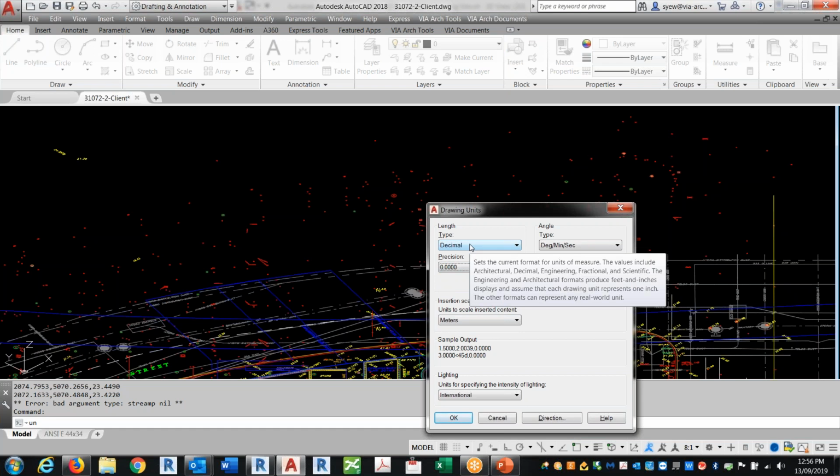Okay, the number, that's the most important thing, because if you put it inside Revit, it'll tell you what number they're supposed to be. If it's feet, square meters, or something else, then you can tell it it's feet, it's meters, or whatever. If you don't do this, Revit just will not function. If you give it, let's say, architectural, it will produce feet in the number, and when Revit translates that, it just doesn't understand.